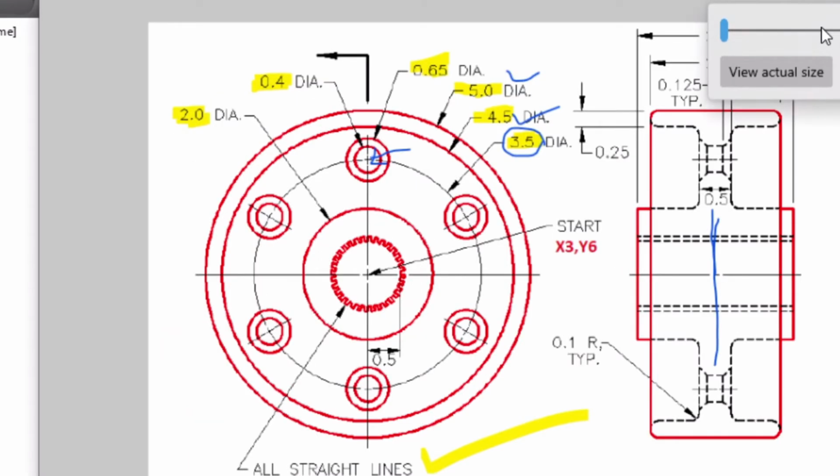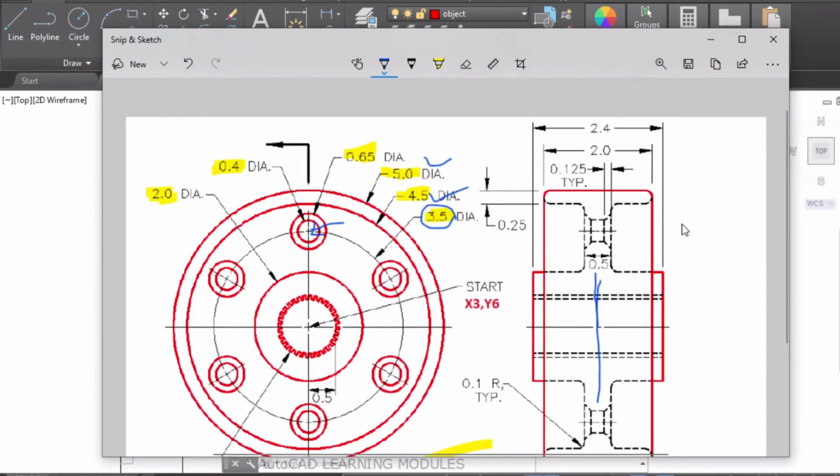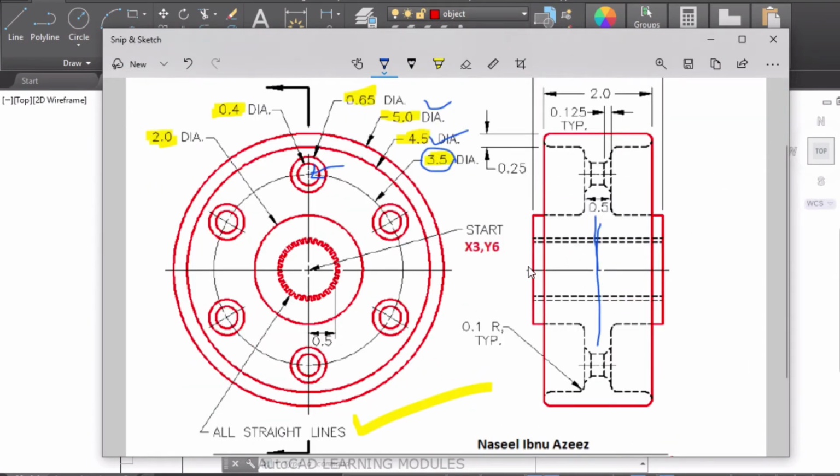It is very clear that you can make use of the mirror tool in this drawing, because if you check the top half of this sketch, it is exactly the mirror image of the bottom half. So what we're going to do is make the top half and then use the mirror tool to mirror it down. So now, just think about everything above this vertical axis.